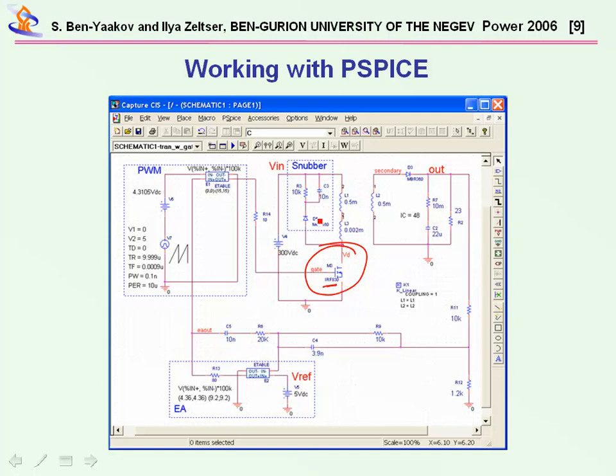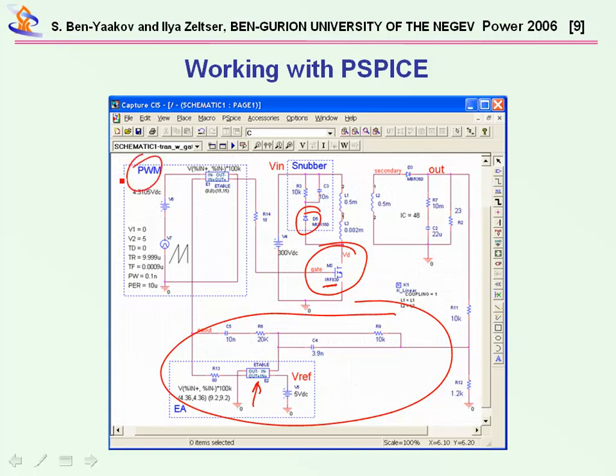There is a real diode. And then we have some behavioral parts. For example, the error amplifier is implemented by a voltage-dependent source. And the PWM generated is also realized by a waveform, a sawtooth, and a dependent source. Actually, it's emulating a comparator.